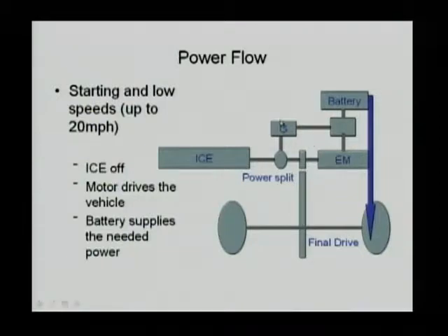In the Prius hybrid, in many other hybrids like the Highlander itself, or even the Ford Escape and American hybrid, the Ford Fusion hybrid, the Nissan Altima hybrid, in all of these hybrid systems, they use a planetary gear-based, very similar torque split system. So at the starting, if you look at the chart, the engine is off. Only the electrical motor is powering the wheels.